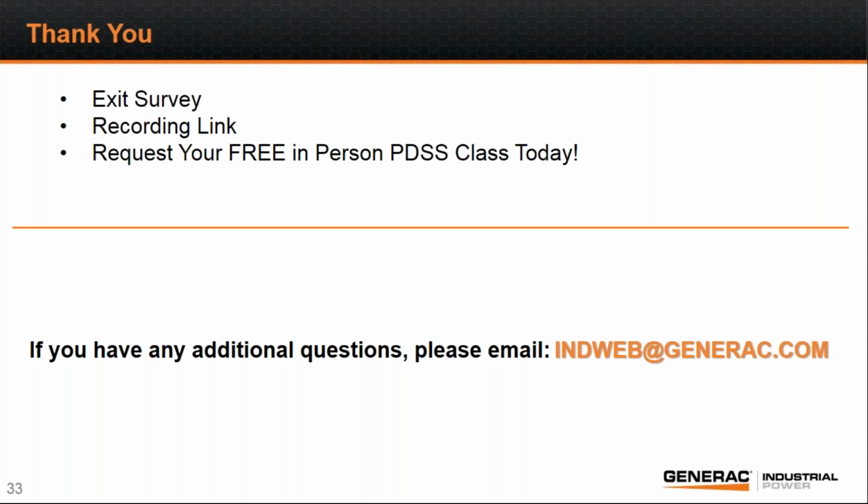All right, and our last question today is, how does a PF other than the gen rating affect the alternator and engine? The PF being the power factor. So power factor of the load, generators are rated to run anywhere from 0.8 lagging up to unity. They're not necessarily rated for leading power factor. So our biggest problem tends to be on the leading side of things. So that's usually the only thing from a power factor discussion you need to be aware of.